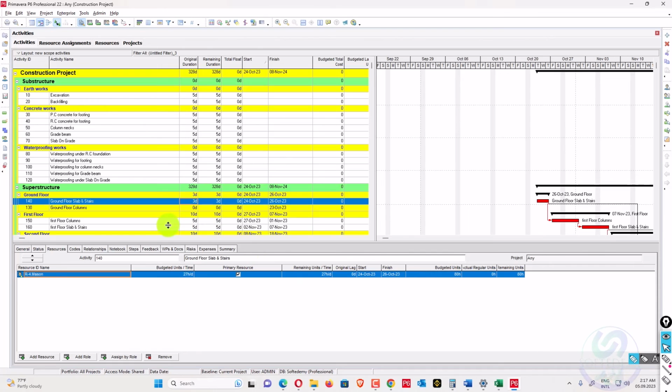It's not like that. If you don't know what the quantity is, how can you apply freely? Like I will apply 2 masons and 1 laborer per day, or 3 masons and 6 masons per day. It's not logical to apply some manpower randomly. There should be some plan, and there should be some limit of budgeted units. So how many budgeted units have you planned in total? You will convert that: for 3 days I require this, in the first 2 days I require this, and on the third day I require this. So you cannot apply it randomly.